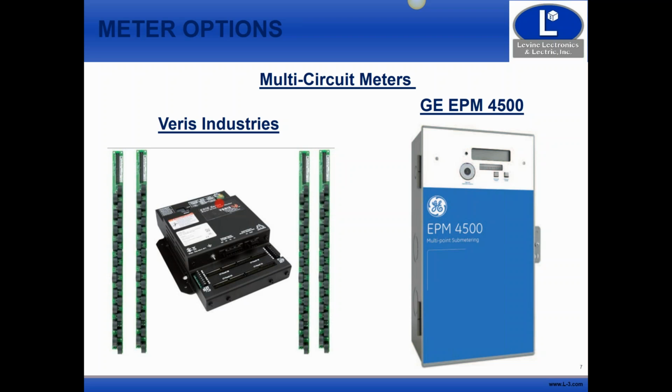Okay, so when we look at this, let's just call it 20. You've got 20 panel boards. They're all separated out. So we're going to monitor or meter these at the main breaker or at the main level of each panel. Okay, we're not going all the way down to individual circuits.